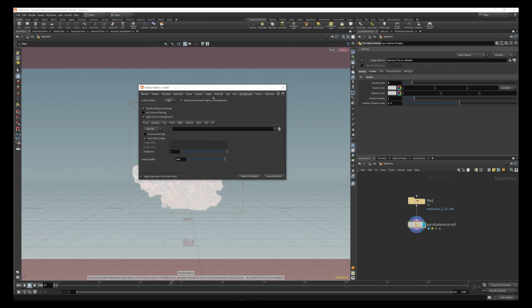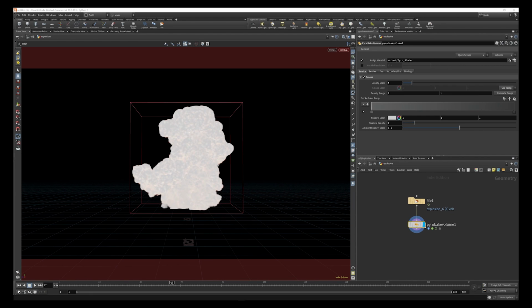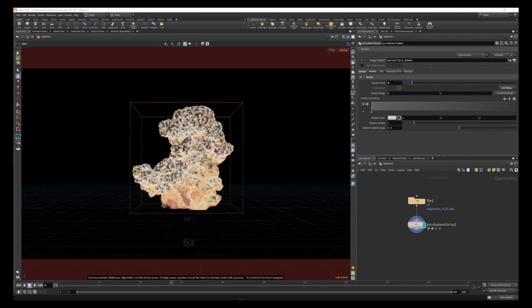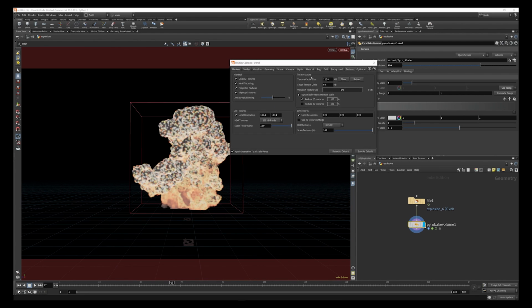I'm going to click D on my keyboard, change the background to dark. Let's click on ramp, use ramp here. As you can see, this looks pretty low res, but it's actually a decent resolution simulation. So under max vis, let's click this on, make this 350. And I think we're still being limited by our overall settings. So I'm going to click D on the keyboard again, come over to texture, and let's set the limit to 350 here.